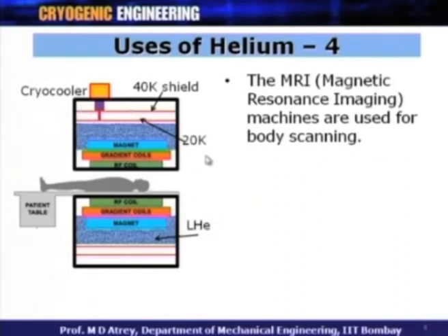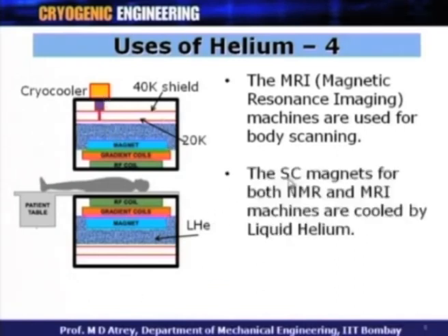Alright. So this is a very important application. In fact, the importance of liquid helium, or the need of liquid helium and a cryocooler, grew because of MRI systems all over the world. The superconducting magnets for both NMR and MRI machines are cooled by liquid helium.